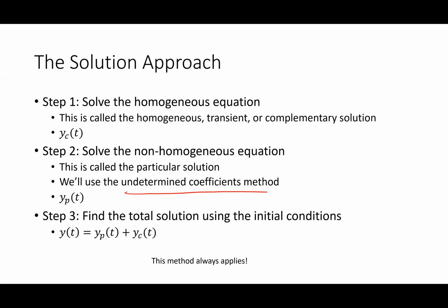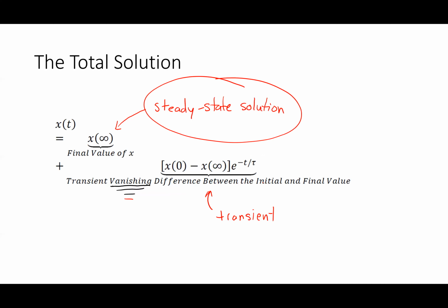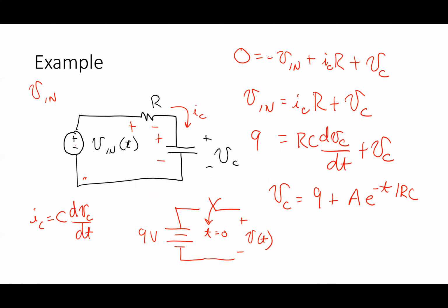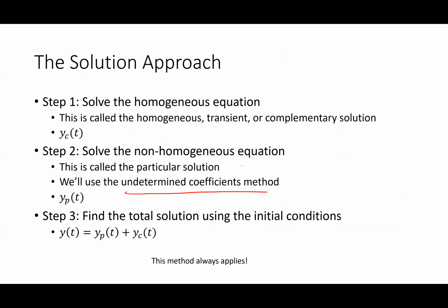All right. Basically, this is where I guess a solution, right? And that guess is pretty easy to do. If I have a circuit that has a constant input, what's the steady state solution going to be? Is it going to vary as a function of time? In this circuit, if I have a constant voltage source, this is my input, what's the steady state voltage on the capacitor going to do? Can it vary as a function of time if I have a constant input voltage? No. So I guess that the voltage is going to be constant. Constant input, constant output.